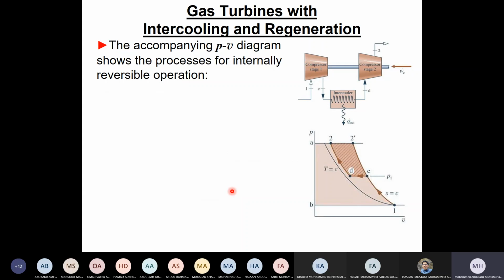What do we mean by intercooling? Intercooling, this is the compression process. This is supposed to be without intercooling. And remember, on the PV diagram, the work is the integral of VdP. So we have P on this axis here. So this is the integral of VdP for the compressor. To get the work for the compressor, it is minus the integral of VdP, and therefore it is the area under the figure on the P axis. So this is the work done here.